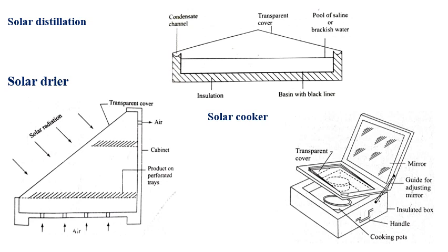The two glass covers are provided to again minimize the heat loss. Thus, the loss due to convection is minimized by making the box airtight, by providing a rubber strip all around between the upper lid and the box. Some insulating material like glass wool or paddy husk or sawdust or any other material can be filled in order to minimize the heat loss.